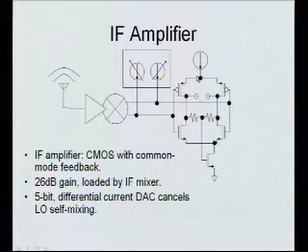And then that's followed up by an amplifier. Again, it looks like CMOS inverters. My philosophy on this is that almost all CMOS is based on digital, and the basic digital block that they're trying to optimize is the inverter. So if you're trying to push on the power limits, the inverter is actually a pretty good way to go because it's been optimized. So here it is. All of these are running in weak inversion, so they're all sub-threshold or sort of middle inversion.